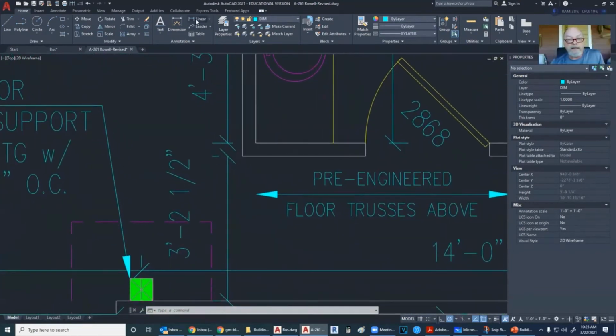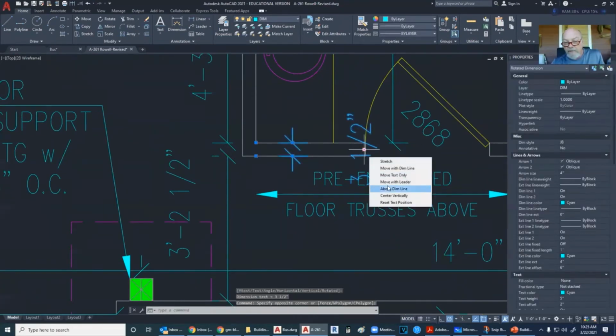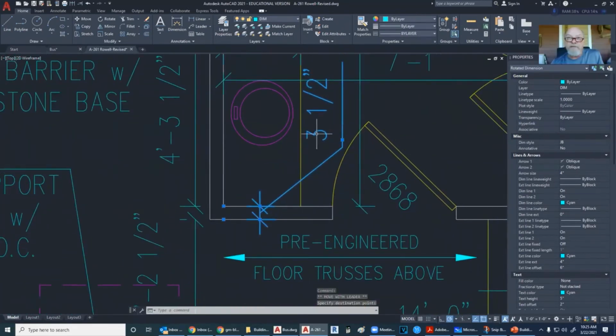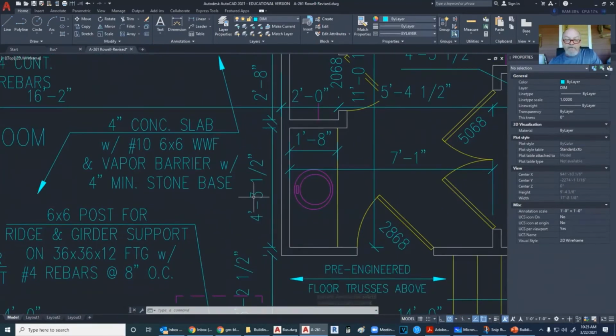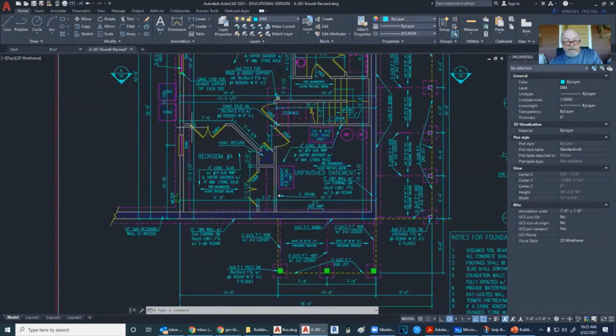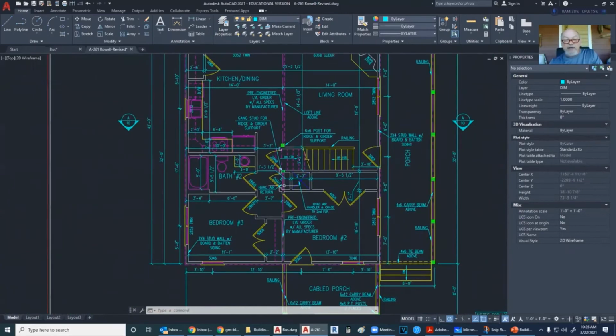Okay. Well, maybe I'm missing what I'm trying to ask. Okay, I put all the odd dimensions in the closets and halls. So when we're building, we're working to 3.5 inch and 5.5 inch. A 2x4 and a 2x6 have that 1/2 inch on there. So when we're placing walls, if I come up with a dimension of 4'3" 3/8 or 4'3" 1/16, I'm going to move that wall so that a 1/2 inch is the smallest increment that I have. And if you look at anything on this, even on the first floor plan, you're not going to see any dimension less than a 1/2 inch.